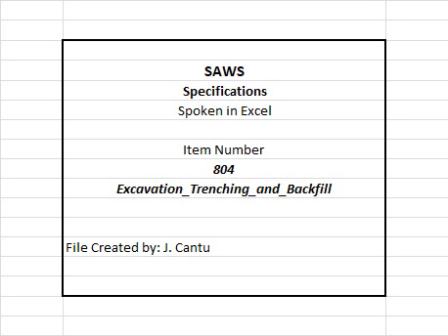Trenches in paved streets shall be covered with a temporary all-weather surface to allow for vehicular traffic and protect trench from weather, water infiltration, and runoff until the final asphalt/concrete paving is complete. 1. This surface shall be a minimum of 4 inches hot mix cold lay compacted and rolled asphaltic black base, either hot mix or cold mix applied, or plates with cold mix asphalt installed around the edges. 2. It is the contractor's responsibility to maintain this surface until the final street restoration is complete. 3. Sections limited to 200 feet of open trench at a time.